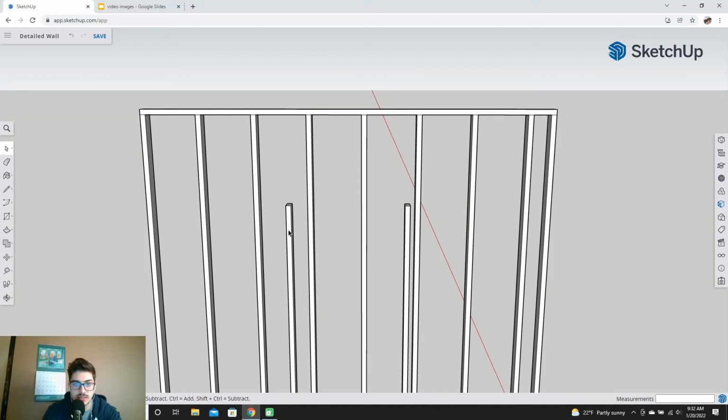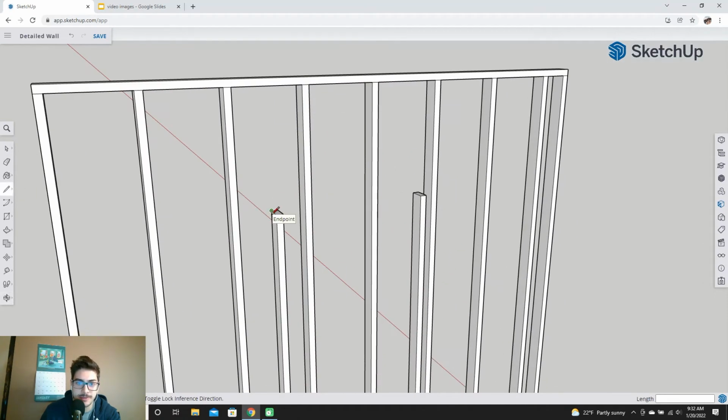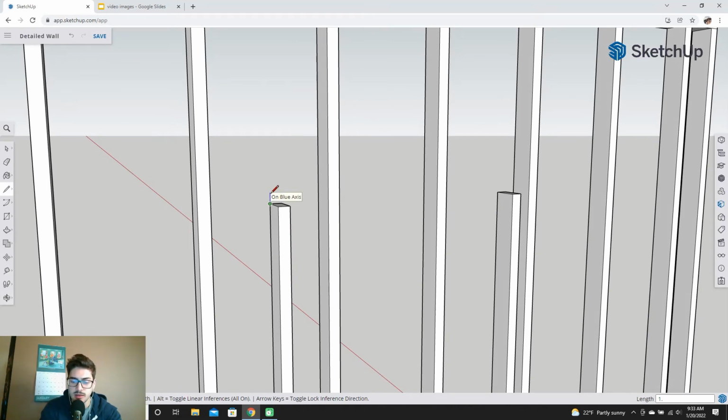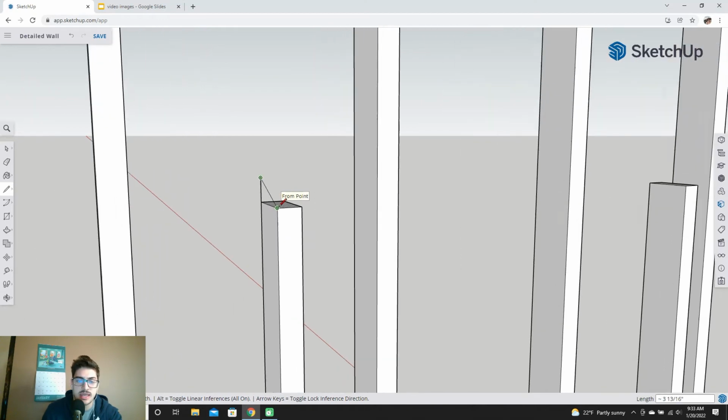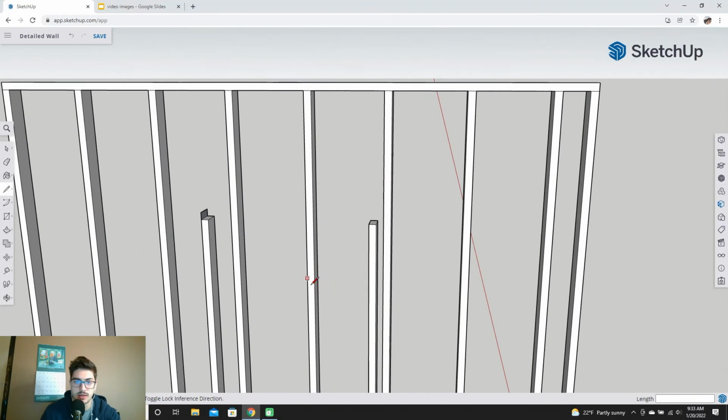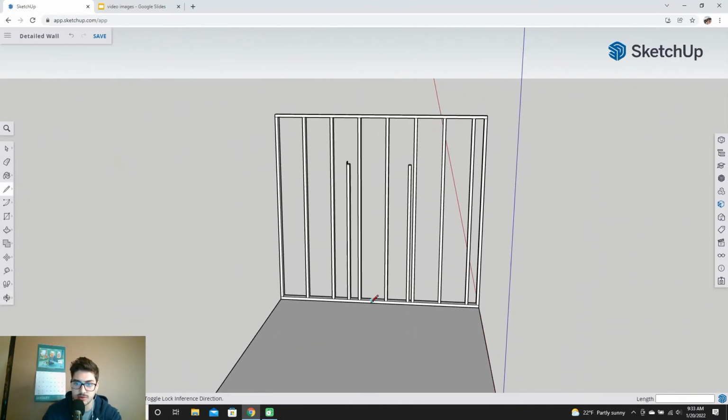The reason you need these to not go all the way up to the ceiling is this also changes whether or not the wall is structural. I should probably put a disclaimer in here: I'm not going to act as your licensed structural engineer, so nothing I say in this video should be taken as absolute fact. Don't sue me for anything. But if this is not a structural wall, then you can just put a flat 1.5 inch 2x4 on top of this guy, and you don't need to make it a beam that can carry significant load. A flat plate, just like what's down here, will work.